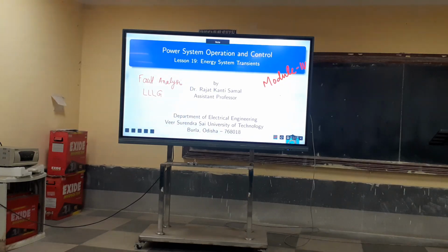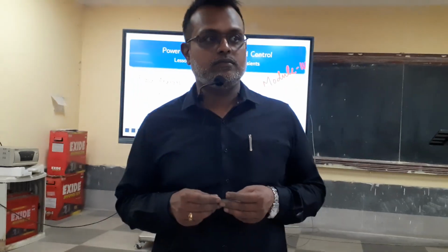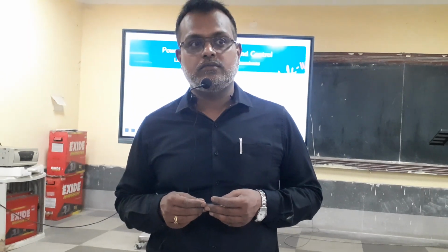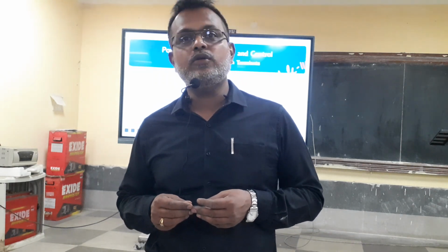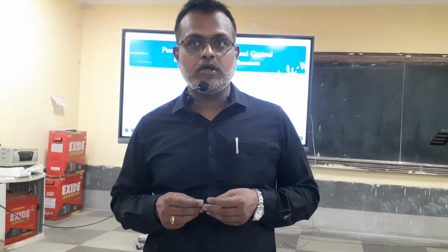Okay. But when we do fault analysis in power systems, we are going to use only symmetrical faults. Why? When we do fault studies, we generally go for symmetrical faults, not unsymmetrical faults, though unsymmetrical faults are the most common. Okay. Severity. We need to design the power system so that it can withstand the highest possible fault level, so that we can decide circuit breakers. Okay. So symmetrical faults are generally used for fault studies.